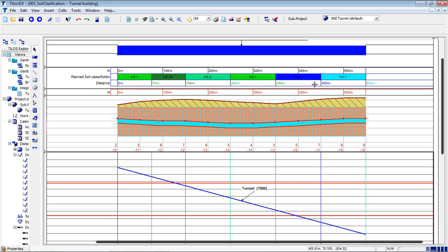These zones give me an understanding of the different types of soils that will be available in the tunnel. Because of the type of soils, it can be an easy area, it can be a difficult area. It will directly impact my TBM performance.